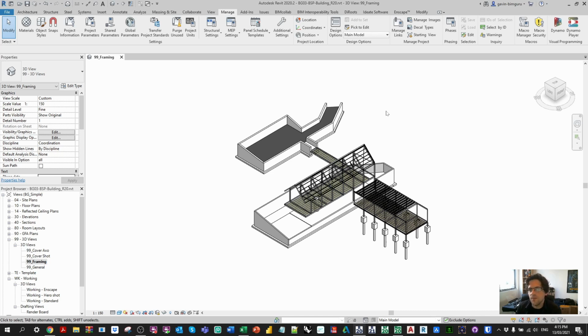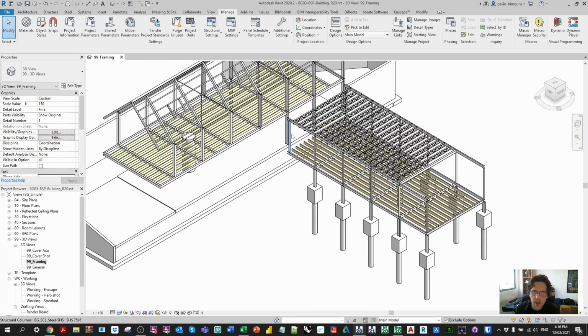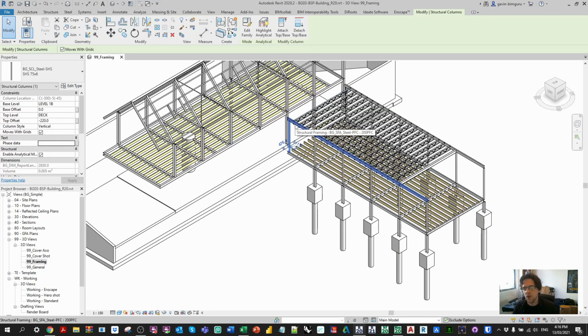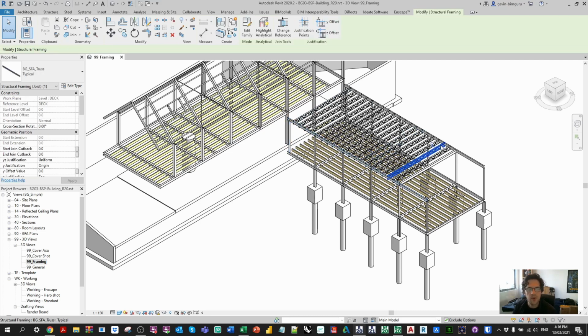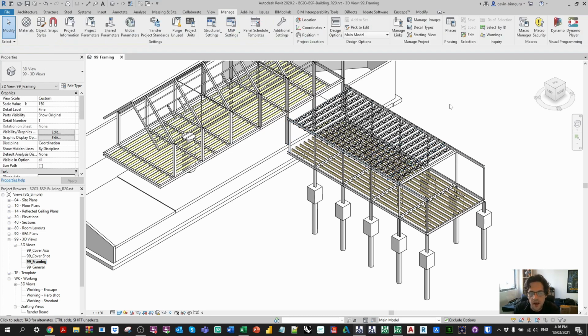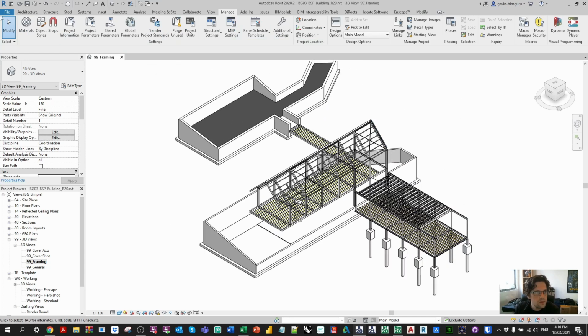Now, you can use two types of sets to associate these elements when you're in Navisworks based on their properties. There are selection sets and search sets. Search sets will find new elements that satisfy the criteria of the filter, whereas selection sets are exactly what you assign to them in Navisworks. Now, we're going to use a combination of them. You probably could use entirely search sets because this model is quite data rich. It's just that sometimes it can be hard to pick up multiple elements in the same set, especially when they're working cross-category. So in this case, let's just export this model.